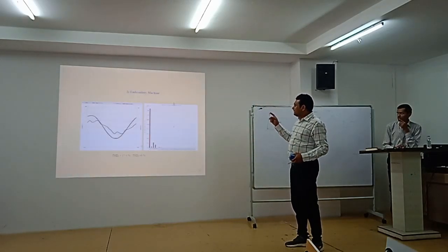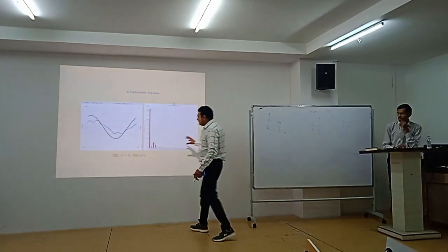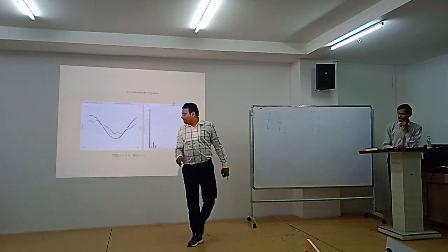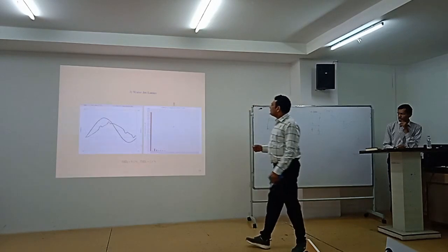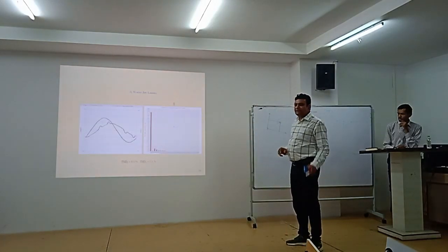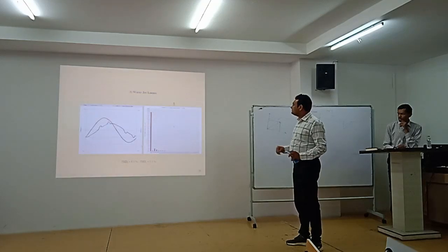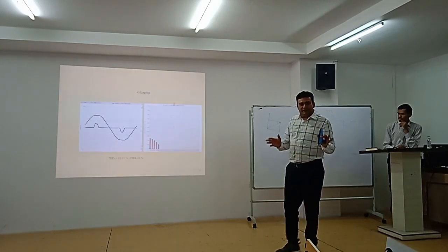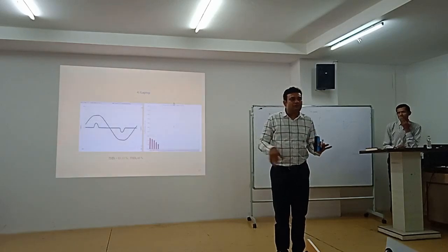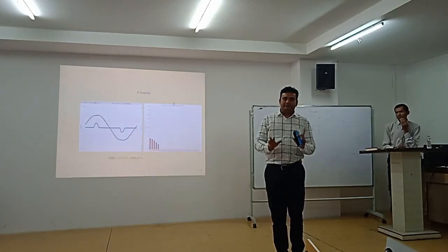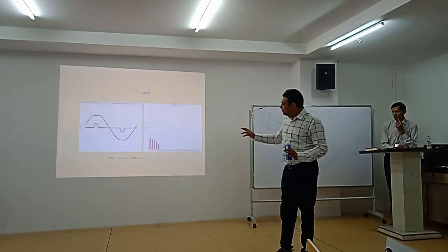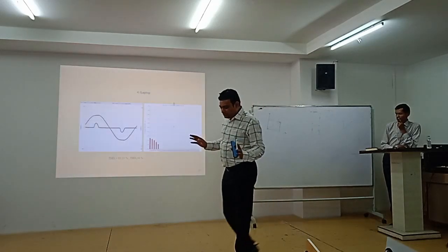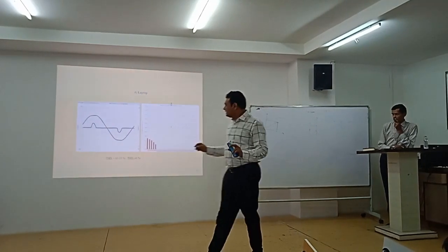Next, embroidery machine. In that also we have taken THD current 70.4, THD voltage 0%. Next, I have taken a few observations of THD current and THD voltage. Next, water jet looms, the load which are available in Surat or industries around Surat. There we went ourselves and with Torrent Power's Yokogawa instrument we have taken a measurement. So current and voltage measurement we have taken. Why?